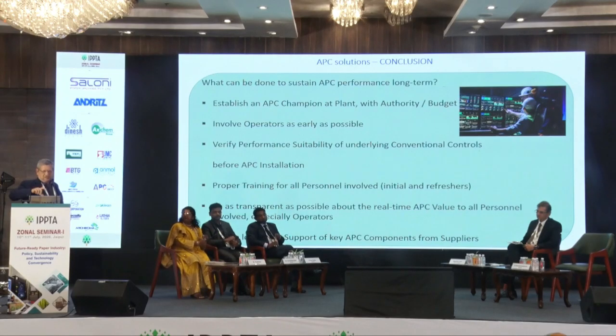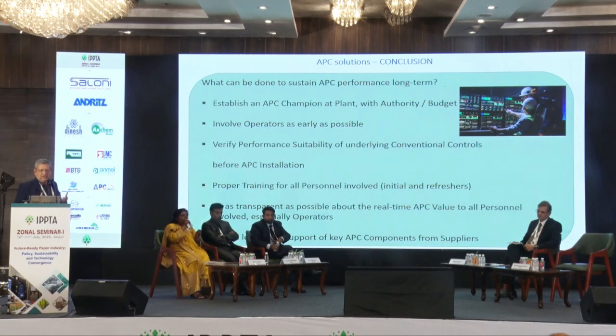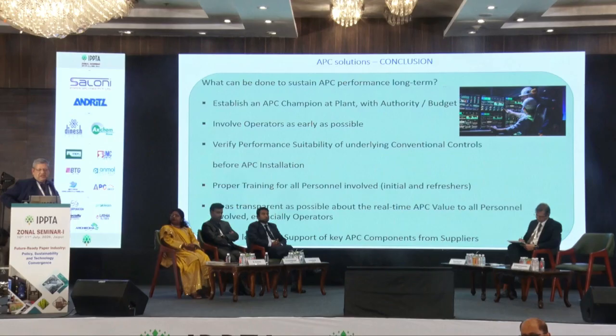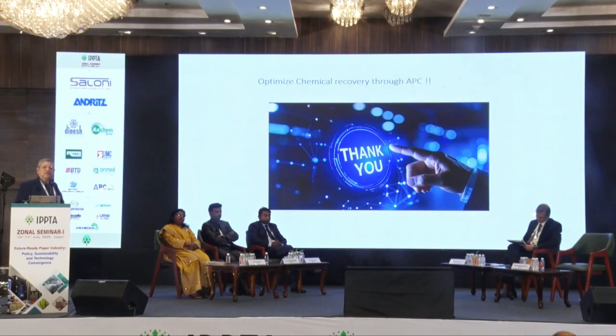Most important in the conclusion is how to sustain the APC. So you have to involve the operator and the management directive should be there. You have to ensure performance stability and underlying conventional control for APC. Very important point: training, and then securing long-term support of the APC components, whoever supplied them. So these are certain cardinal points.